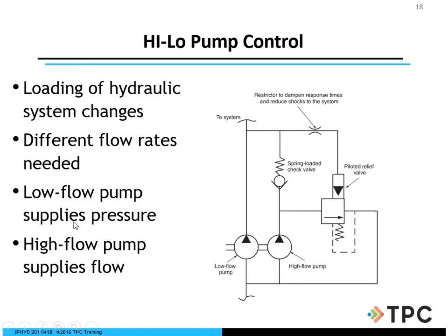Low flow pump supplies pressure, and the high flow pump supplies that flow. So when you use two pumps like this, we're maintaining our system pressure throughout. You'll see this in a lot of complex applications. And we have a spring-loaded check valve all the way through here to the pilot relief valve for this guy. And everything here is going back to the tank.